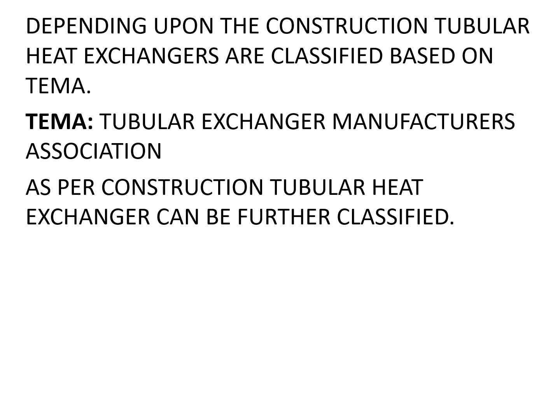So if you want to design the tubular type of heat exchanger, the mechanical design can be ASME Section 8 Division 1. So we call it the UHX section. UHX, that is U stamp. HX means heat exchanger in the division. But you can also go to U2 stamp or U3 stamp depending upon the pressure requirement. Mechanically it can be designed with ASME. But if you want to size it properly, then you have to go to the TEMA specification or standard.